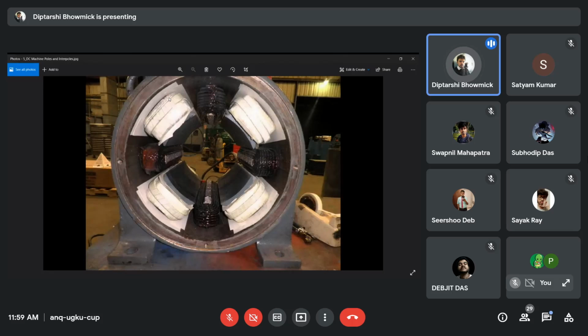One is thin wire, which has an enormous number of turns. And you may see another type of winding where the conductor is thick, not so thin, and a few number of turns, 2 or 3 turns, or 5 turns, or 10 turns are given there. You can actually count the number of turns. So a thick winding with a lesser number of turns, and a very thin wire winding with a huge number of turns. You can find two types of winding in a field coil.